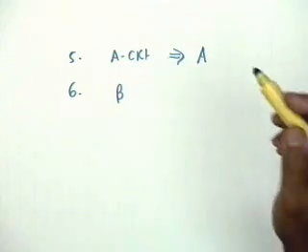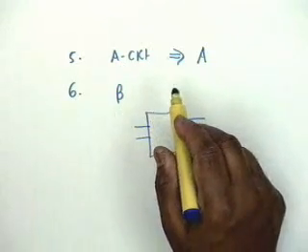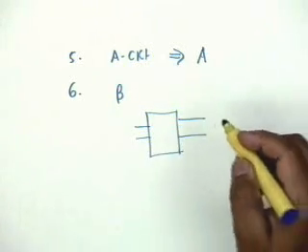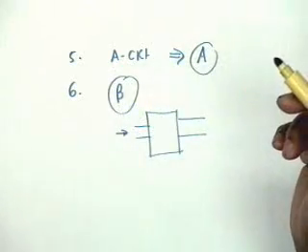It is always good to remember that in the absorption of RS and RL, and in the absorption of feedback network impedances, the impedance that is seen from the output port will depend on whether the input connection is series or shunt. If it is series, then you leave it open. If it is shunt, short it. Similarly, for what you absorb at the RS end. These are the general rules, and once you identify A and beta, you know the feedback gain, the input impedance, and the output impedance. In the matter of input and output impedances, one has to be a little careful in the calculation.